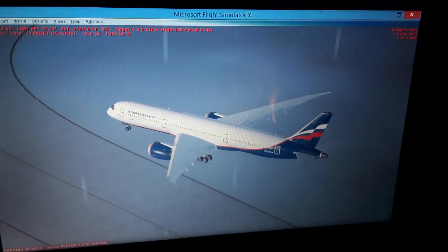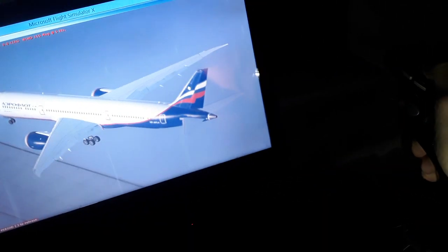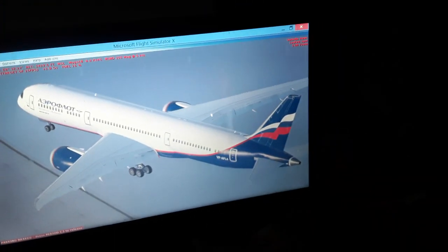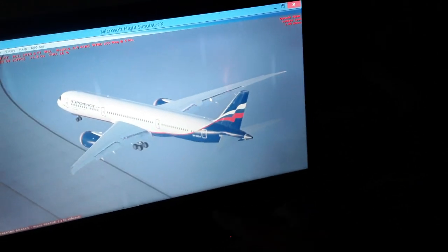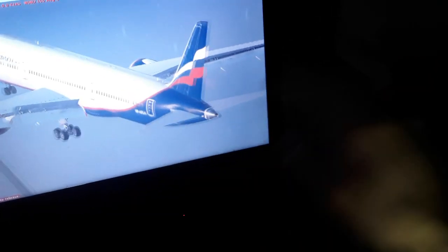The center of gravity is on the yaw axis. Over here we can see the rudder movement, and also the nose wheel, through the center of gravity for making left and right aerodynamic turns. We also have the lateral axis from wingtip to wingtip, which is the pitch axis. We use the elevator for climb or descent, as you can see on the aircraft.